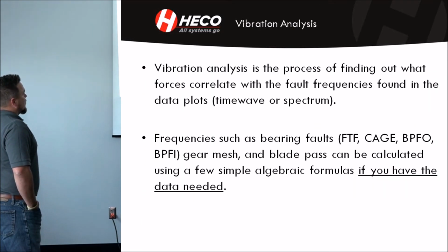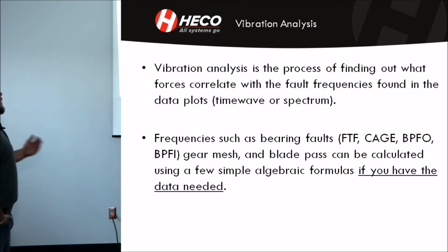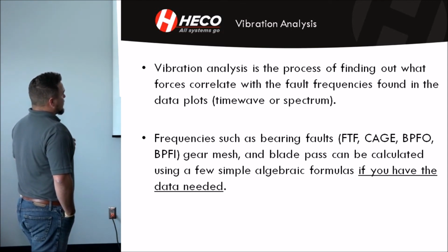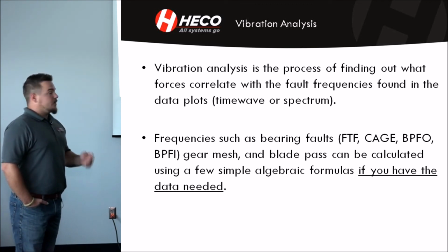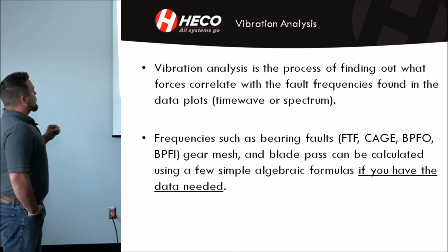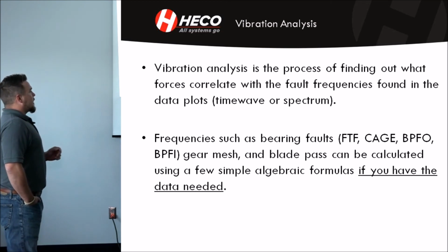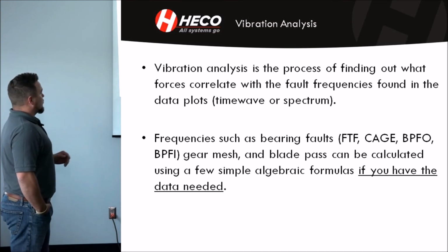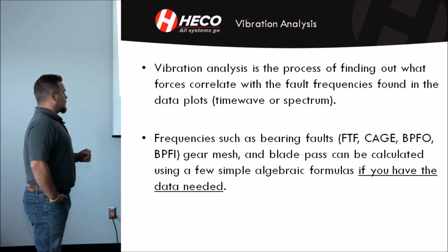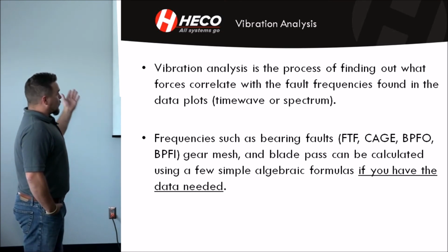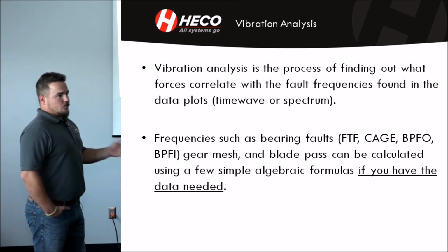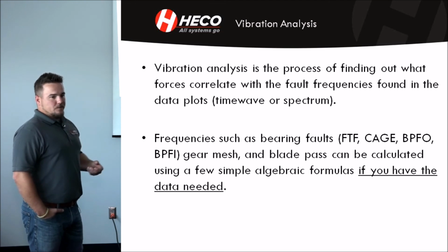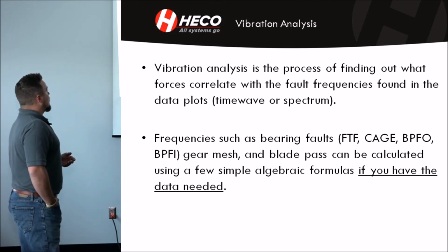All right. Okay, so the definition of vibration analysis. Vibration analysis is the process of finding out what forces correlate with the fault frequencies found in the data plots, either time wave or spectrum. Frequencies such as bearing faults, FTF, cage, BPFO, BPFI, we already talked about all those, gear mesh and blade pass, can be calculated using a few simple algebraic formulas if you have the data needed. In order to calculate gear mesh, you need the amount of teeth on each shaft so you can calculate down actual intermediate shaft speeds as well as the gear mesh frequency itself.